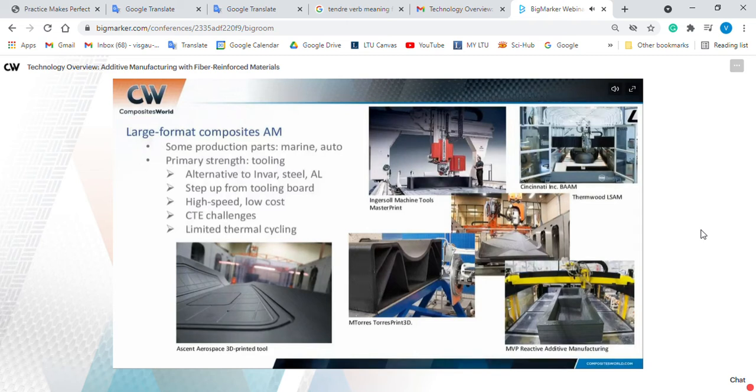All right, there's a question here about carbon nanotubes or carbon nanostructures or fullerenes inside powders for additive manufacturing. The question is, are there any significant cases in the strength or fatigue results of the parts? I've not seen that. There's certainly no reason why you couldn't functionalize carbon nanotubes within a resin matrix the same way you would in a traditional composites manufacturing process. But I've not seen significant data on that yet.